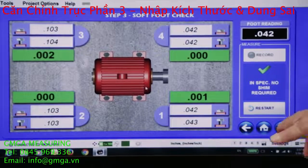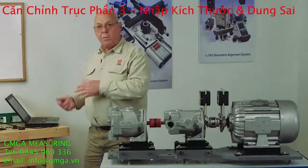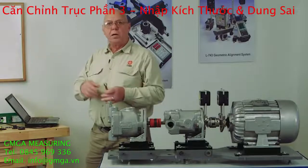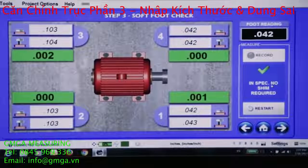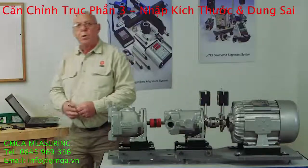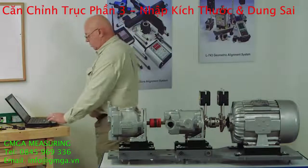To go to the next step, we just click on the right arrow. If I click on the back arrow, it takes me to the previous step. Or if I click the home button, it takes me to the home page. This says inspect, no shim required. But if I clicked restart, all that data would go away and I could do a soft foot check of it. A couple, 3 checks to make.